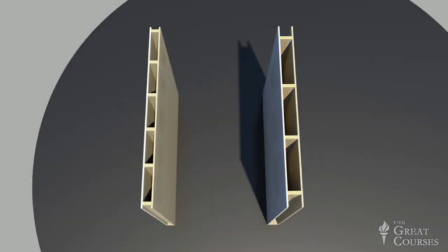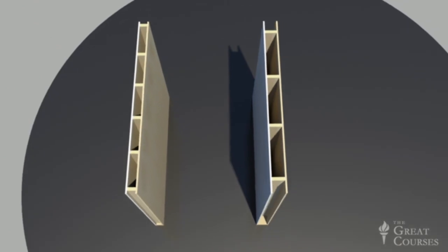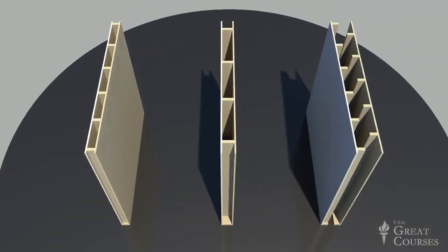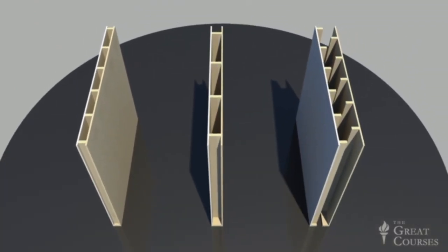This change doesn't adversely affect the wall's structural integrity, but it greatly improves its potential thermal resistance by providing space for another 2 inches of insulation, while also reducing the proportion of wall area susceptible to thermal bridging. Advanced framing has the added advantage of reducing the total required quantity of lumber by about 25%, making it cheaper and even more attractive from a sustainability perspective. The disadvantage of advanced framing is that it's still susceptible to some thermal bridging.